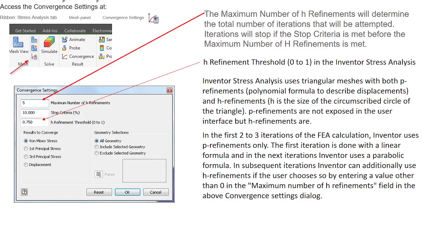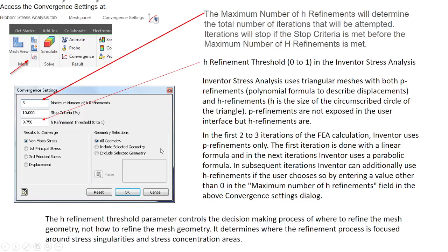It sounds good, but it requires much greater calculation time and very powerful computers. Only at the places where the stress is highest or closer to the higher value. In this example, if the stress is 75% of the maximum stress at that point, in the vicinity of that point, use smaller size mesh.